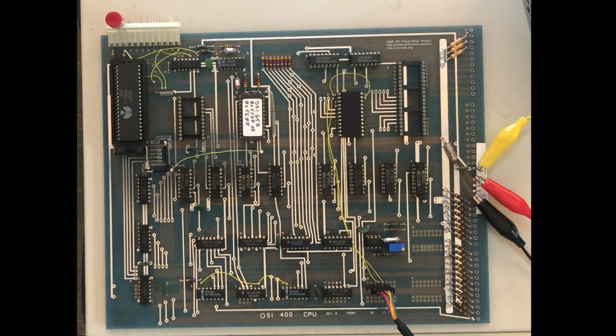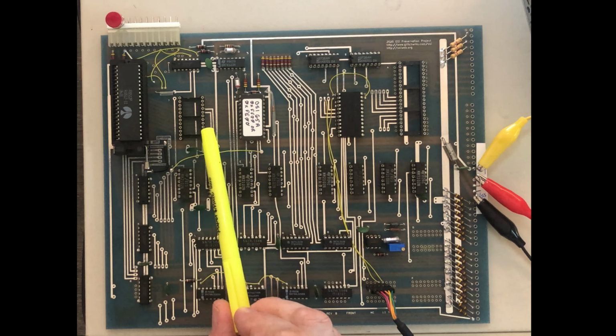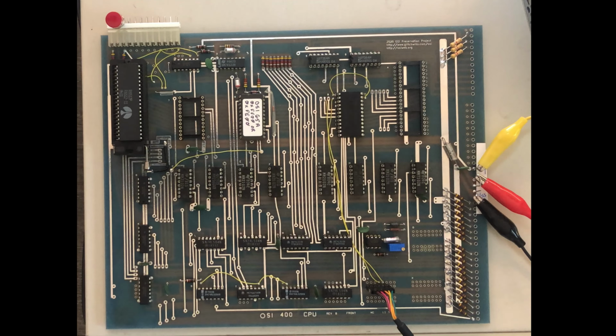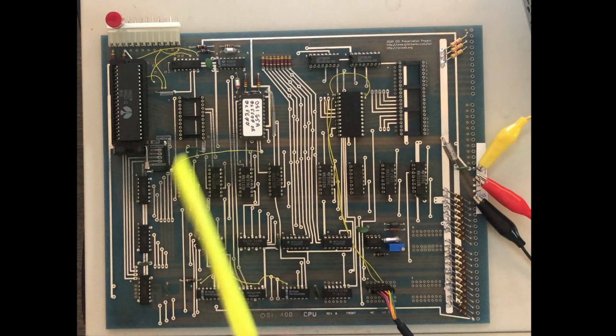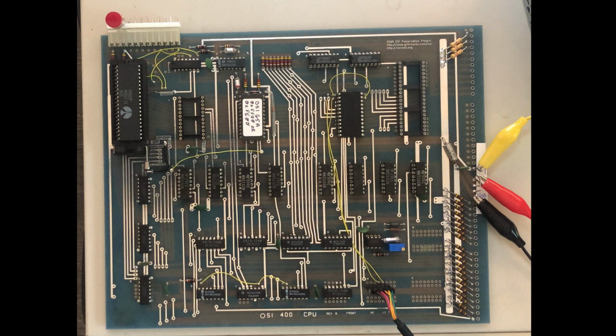Don't know there's a whole lot else to say here. There's an empty socket here, I guess, or this empty socket could take another 1702 EEPROM if you wanted to. This is known as the M socket for monitor and the U socket for user program. Anything else I haven't explained here? I guess there's some open footprints over here for additional logic devices or whatever. I just use one of those, like I say, for the TTL RS-232 I/O. I think that pretty much provides the introduction to the board.